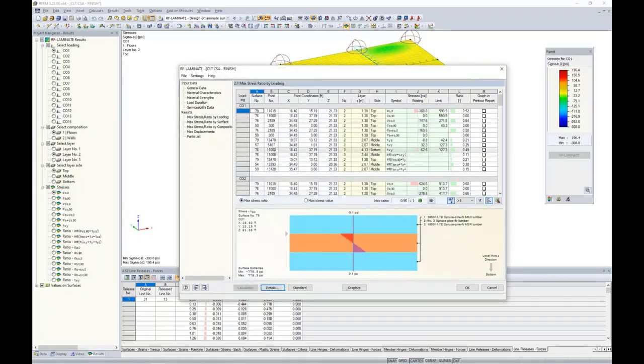So once you've applied the average regions, come in here and check on this checkbox. You can run your calculation again, and now we take a look at our max design ratios, and we see a max check now of 0.9. So that was significantly reduced from 1.81 clear down to 0.9 just by applying average regions and those FE mesh refinements, rather than increasing the thickness of our panels or decreasing loads. So that is how you essentially can deal with singularities with CLT design.